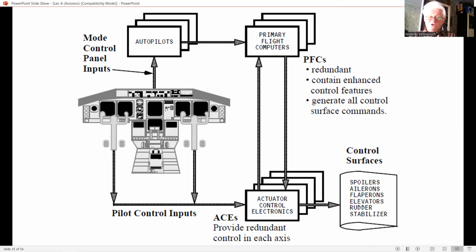Apart from the cost of the additional channels, the overall system MTBF is reduced, and hence the system availability is lowered. While it may be acceptable to fly with one failed channel, assuming sufficient redundancy, the impact on availability is obvious if the overall MTBF is too low.